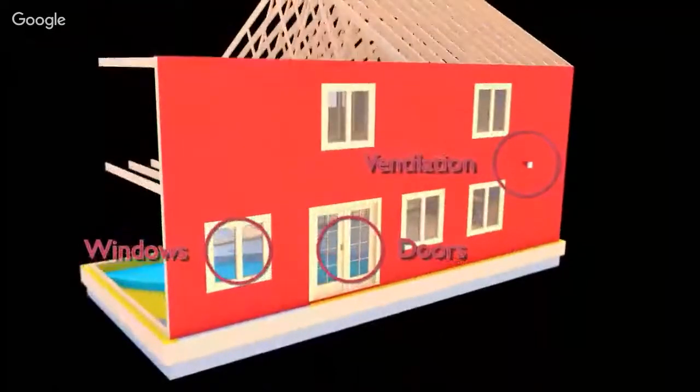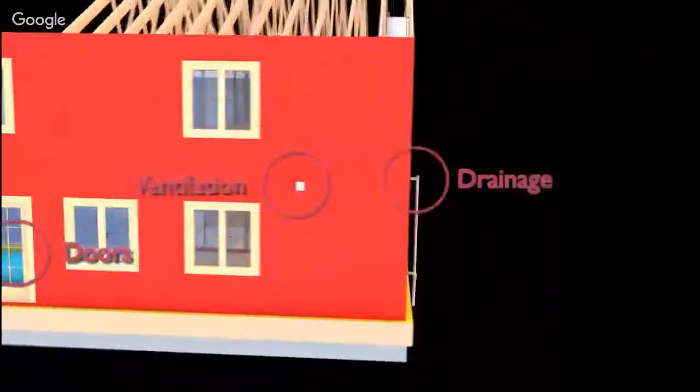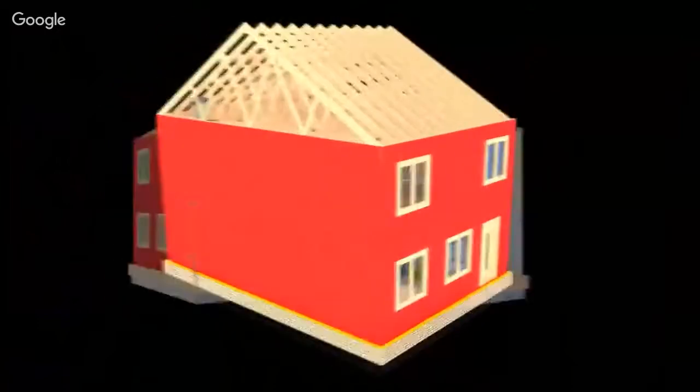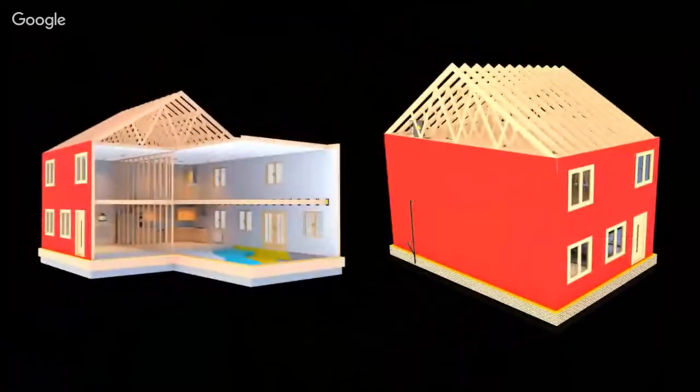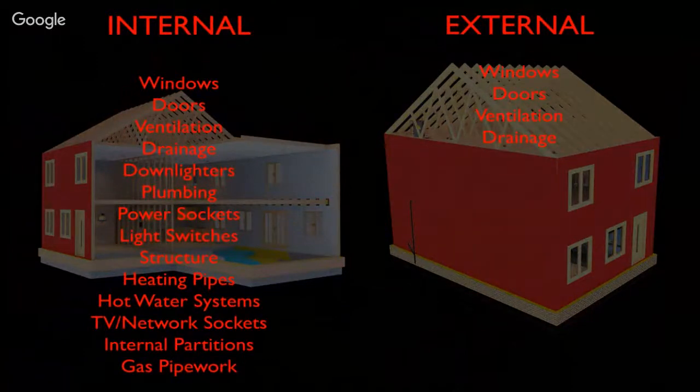So moving the air barrier or airtight layer externally hugely reduces the amount of sealing required, and that increases the likelihood that the air leakage targets will be met. Basically, this allows the use of more ambitious air leakage rates at the design stage, giving improved design flexibility in other areas such as thermal insulation.